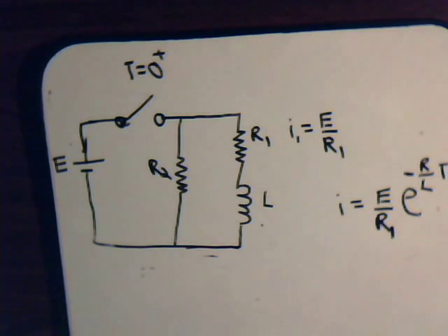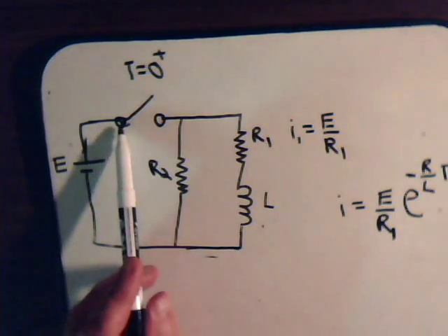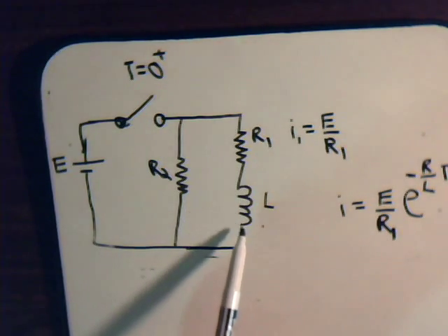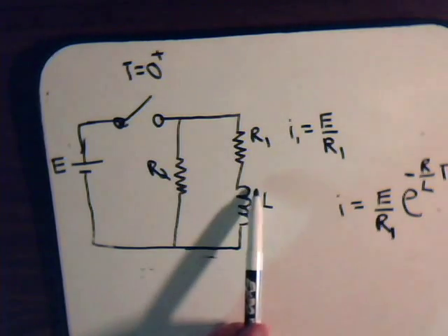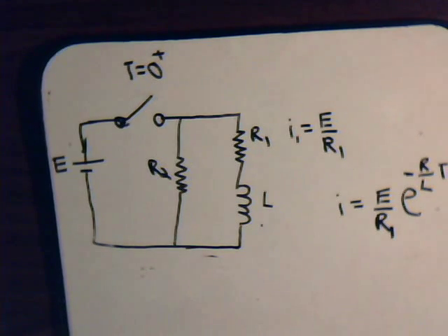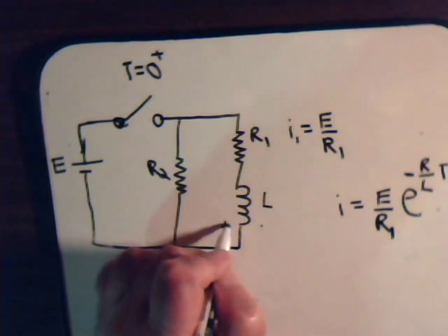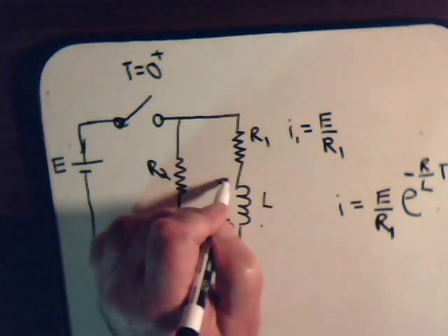Now, as we discussed in the previous videos, when we had this connected and there was a growth current going through here, the induced voltage across the coil opposed that current, and it was plus minus. Now when the magnetic field is collapsing, it induces a voltage of the opposite polarity, plus minus.